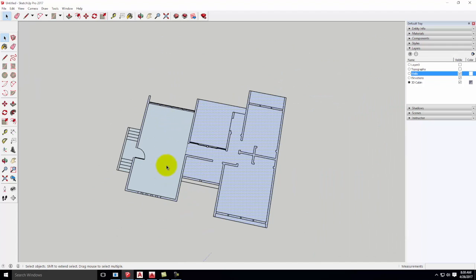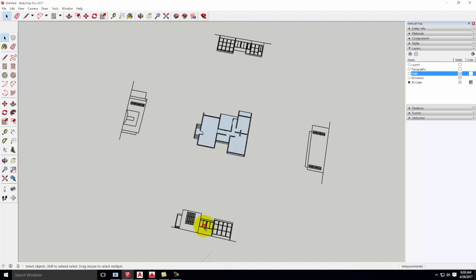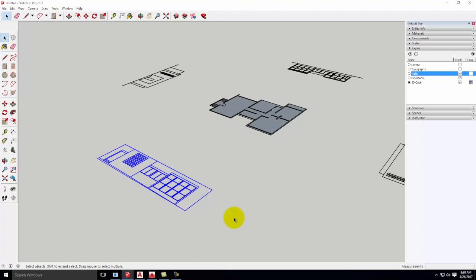Now, it would be helpful to know some of the elevation marks as well. So what I can do is take one of these side elevation components like this, and I'd like to rotate it up into the 3 dimensions that it needs to be in. Now, rotating it in SketchUp can be a little challenging. It gives us this little protractor thing, but it's hard to get it to rotate in the view we want. So one way of kind of cheating the system a little bit is to draw close to your object a little box.